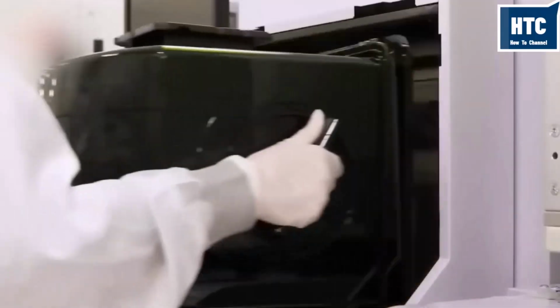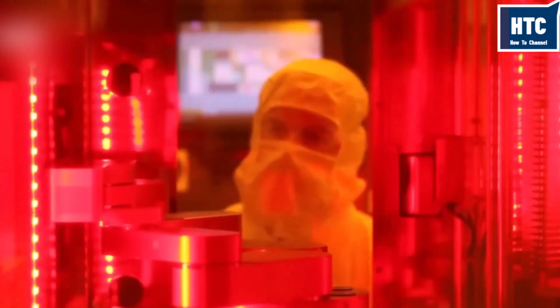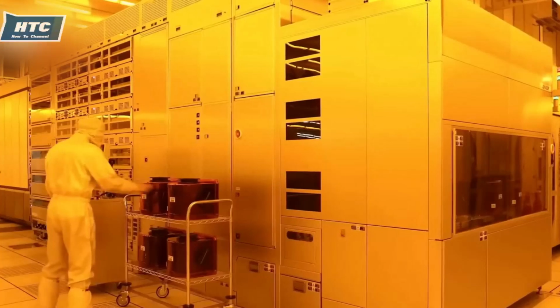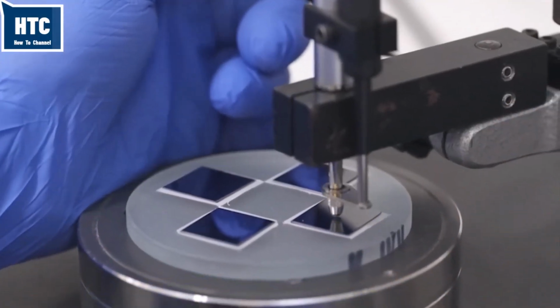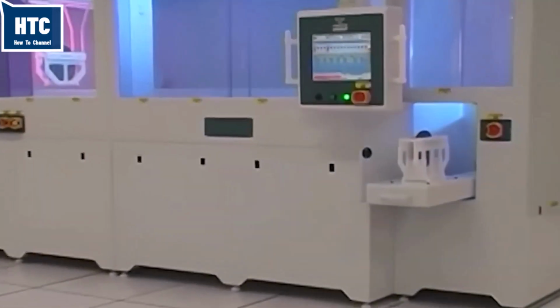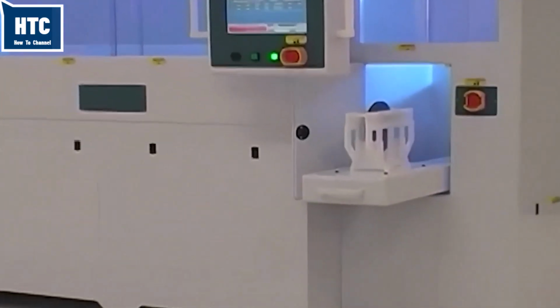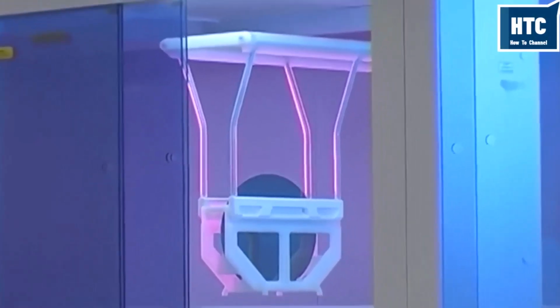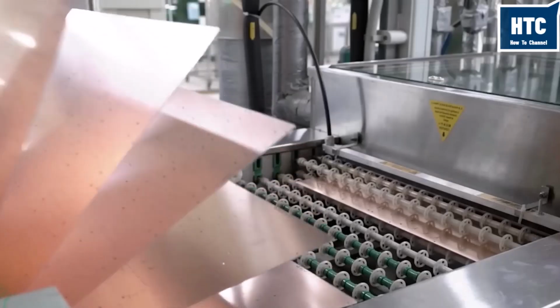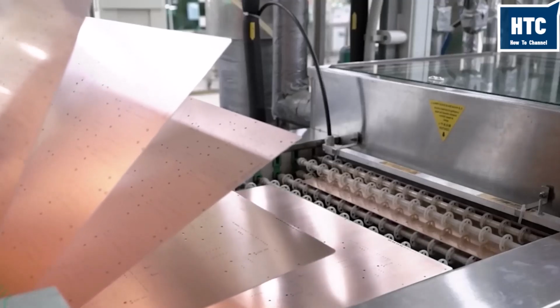Once the billions of transistors are formed, they are useless in isolation. They must be wired together. This phase is called the back end of line, or BEOL. We can't just run wires anywhere. We have to build a scaffold. We deposit a layer of insulating glass, etch holes where the contacts need to go, and then fill those holes with metal. Aluminum was used in the past, but today we use copper for its superior conductivity.